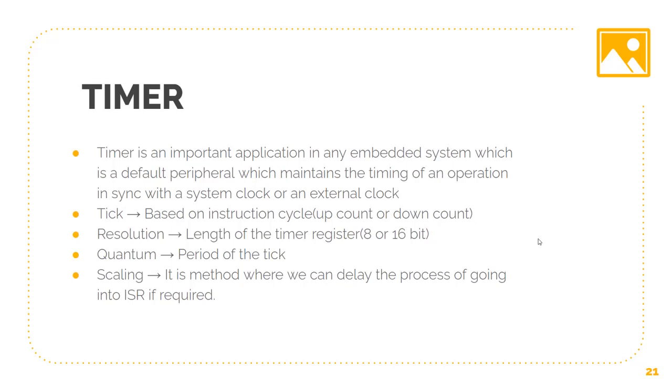The thing about timer 2 is it also comes with a register called PR2. The PR2 register can be set to any value between 00H and FFH. The timer starts counting from 00H till the value of the PR2 register, and once it's done, it overflows back to 00H. Every time it overflows, an interrupt occurs. So we can use timers to count. We can also use timers to run interrupts. Next slide.